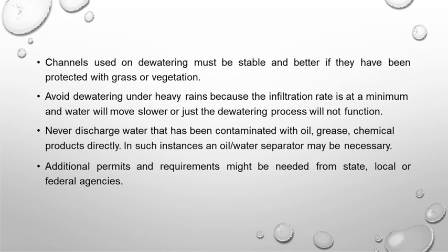Okay, so that is the reciprocating pump, and the double acting pump is where the water acts on both sides of the piston. And the second is the centrifugal pump. A centrifugal pump is a hydraulic machine which is used to raise a liquid from a lower to a higher level by creating the required pressure by means of centrifugal action. That pump is called a centrifugal pump, which increases the pressure energy of the fluid.